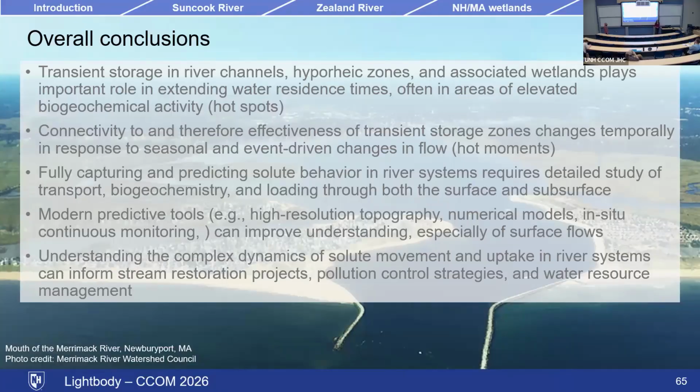He's doing that. For the overbank areas, he's using the LiDAR. In-bank, we're just doing sort of pebble counts and then visual sectioning of that. But you try to at least look at what's there to give you some idea what that number would be. Yeah, he's not planning on doing sensitivity, although you're certainly welcome to encourage him to extend his thesis to do that. But he is trying to do his best at capturing that spatial variability in the roughness.